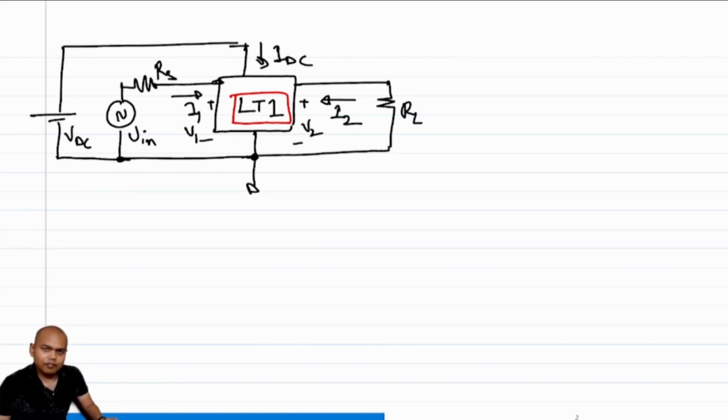One of the properties of time variance is that it can cause a frequency shift of the input. Even though that is not a part of this course, it is instructive to be aware of one of the properties of time variant circuits. A time variant circuit can cause frequency shifts. For example, a mixer is a time variant circuit. However, a time invariant circuit cannot cause a shift in frequency of the signal that it's processing. You will see the importance of this statement in a few minutes.